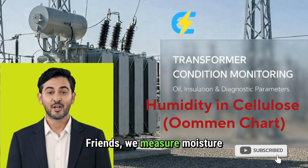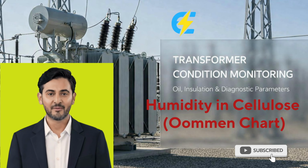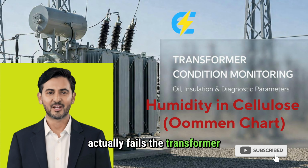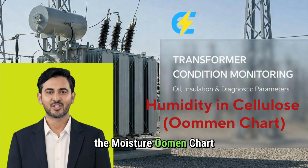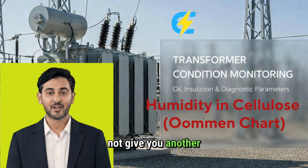Friends, we measure moisture in oil. But moisture damages paper. That gap between what we measure and what actually fails the transformer is where many engineers get misled. This is exactly why the moisture Oommen chart exists. The Oommen chart does not give you another number.